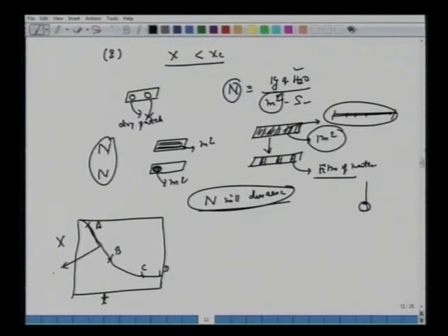We will call it constant rate because X changes linearly. So if we define N as Ss over the total surface area times dX by dt, since X changes linearly, we will expect that this N is constant here. So this region is called constant rate drying. Then of course X changes non-linearly, so in that region N will decrease. So we will stop here.